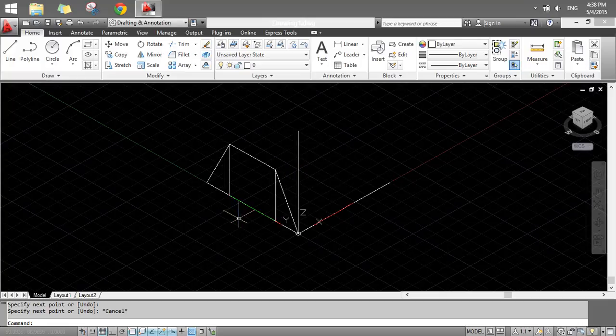Now the depth of this figure was 60 units. So from the above triangle I'll draw 60. I switch on snap mode and ortho mode, click on here, extend it backwards, and make sure the angle is 0 degree. In the units, specify 60, enter. You have a line of 60. Press escape, line, click on here, extend it backwards with angle locked to 0